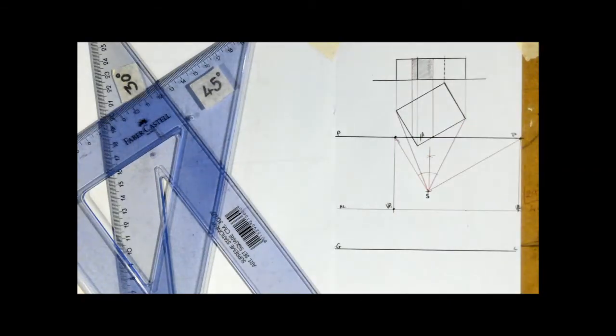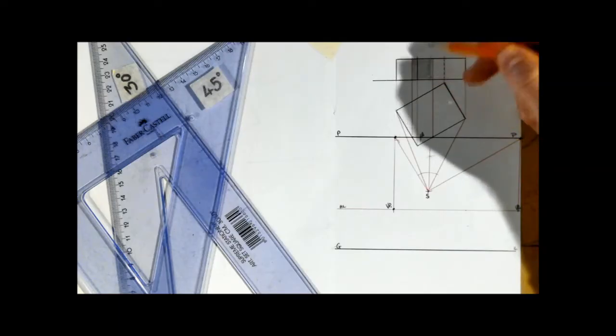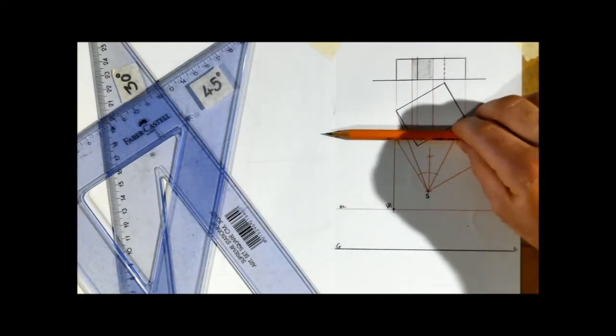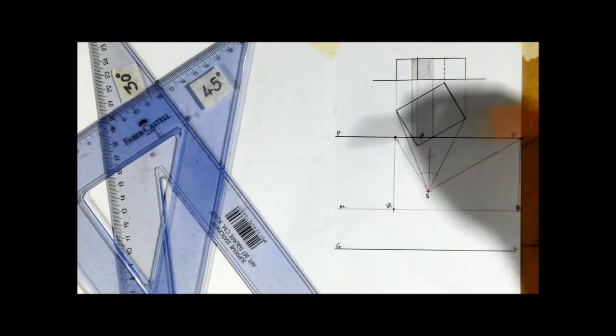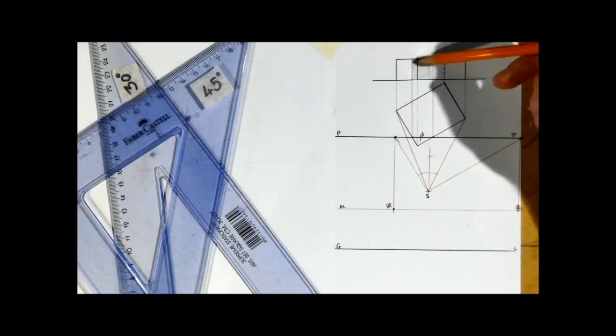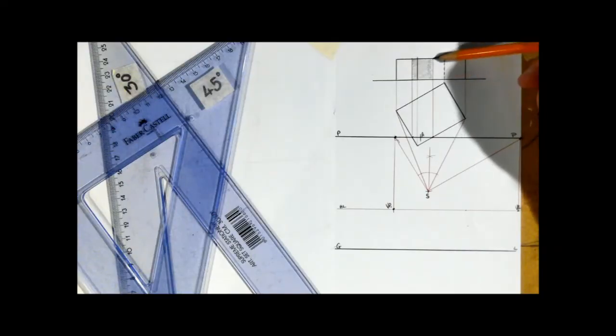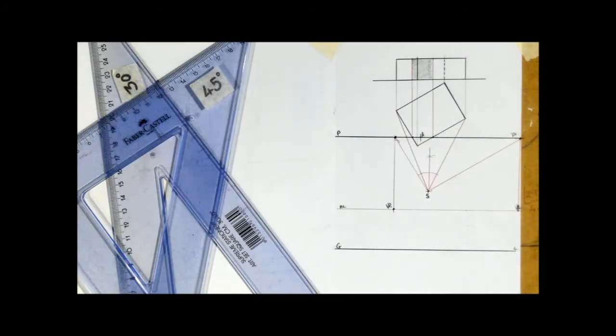Now at that exact box there, as we can see, that is actually where our picture plane is technically cutting through it. It's like it's slicing that part of the box there. Okay, but at that part it cuts it in two edges, this edge here and this edge here, and at those edges we can actually take them as true heights. So they are very, very important points to start a question when our picture plane is cutting through our object.